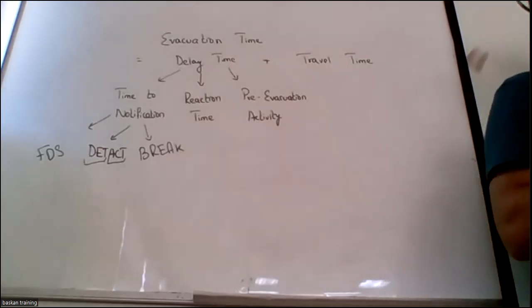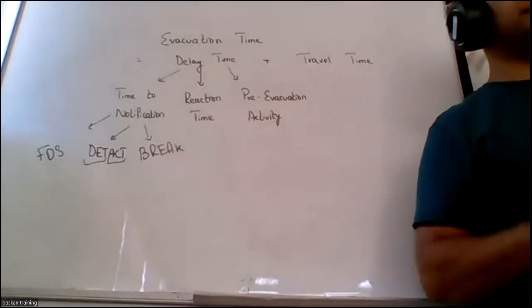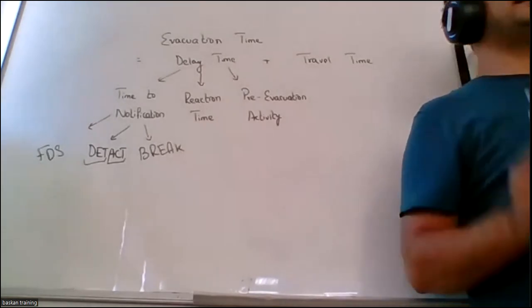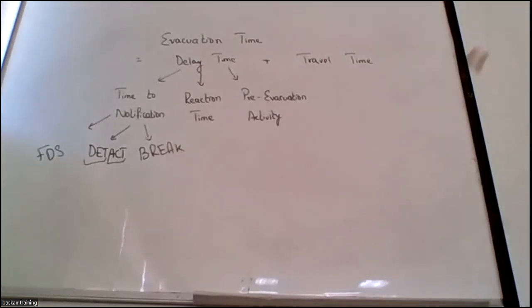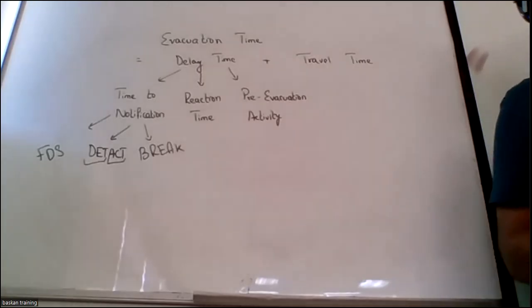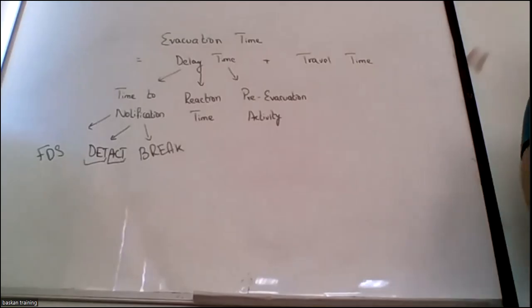Some people may not be able to locate the signs during panicking behavior. In the last lecture, we discussed the exit light color. The emergency exit light can be either green or red. It's not that the code says it should always be green.